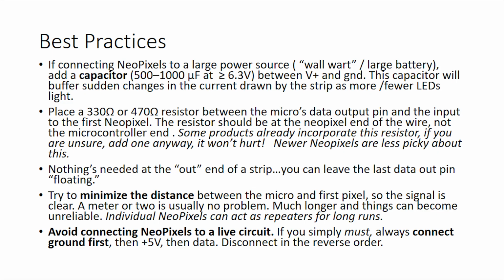You don't need a terminator, I've already said that. And minimise the distance. A metre or two is usually no problem, but individual NeoPixels can act as repeaters. I just explained that one, whereby you can put a repeater in, not to give you light or to be useful, just to clean up the signal and make it better for the other side.